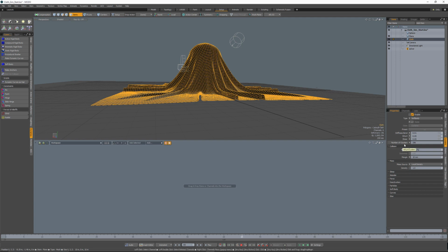Not so much things like the number of clusters, but you can adjust some of these parameters, especially these three here: stiffness, bend, struct, and shear. Friction are also things that you can animate over time. And when we look at closed soft bodies, we'll also look down here. This also can apply to cloth like we've done here, but we have some things like pose matching, pressure and drag. Those will take more effect as we look at a more in-depth look at some of the other options available with soft bodies in a later episode. But just keep in mind, you can animate those.